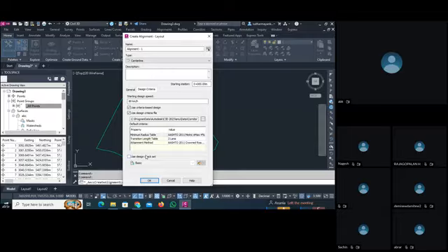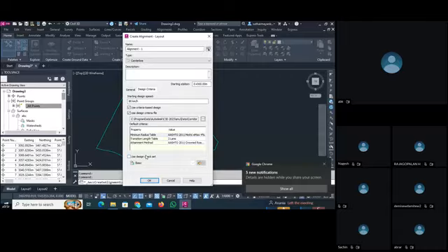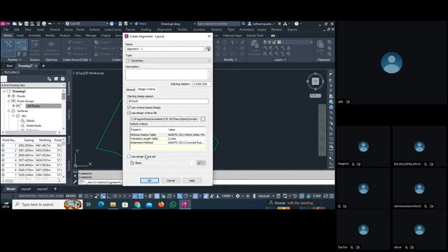But it does not mean you cannot work further if you set the design check set, because design check set is set for our purpose only. If we want that while working on this alignment my radius does not go below 200 meters, then when you go to 201 and you have selected this design check set, it will give you a pop-up that you are going beyond 200 meters. So design check set is checking against the rule, that's all. Now let's talk about the design also.